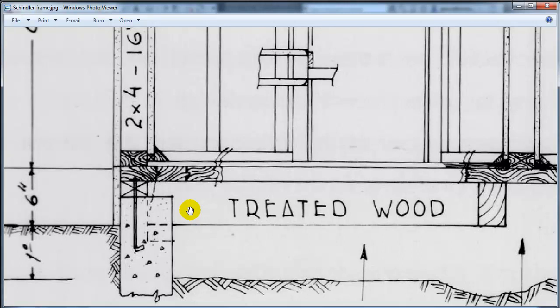What happens is termites and bugs and moisture wick up in there, and we have all sorts of problems where the subfloor has rot problems unless we put a lot of flashing in there. But I'll show you what we do typically, which is to wrap it down a little bit. We typically wrap it down over this 1.5, that 3 inches, maybe 4 inches, maybe 5 inches. Still holding it a little bit off the ground. We like to have a couple inches there, so maybe I'll just bring it down about 4 inches.